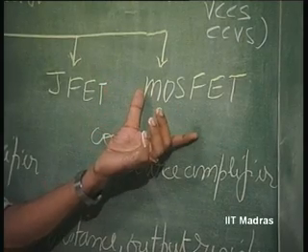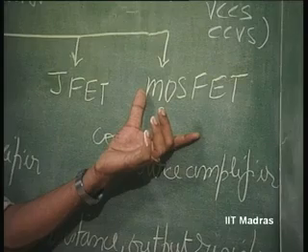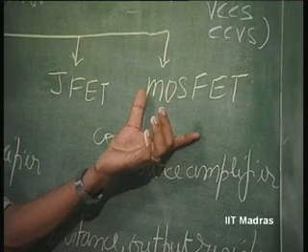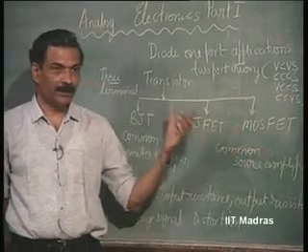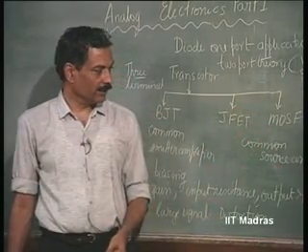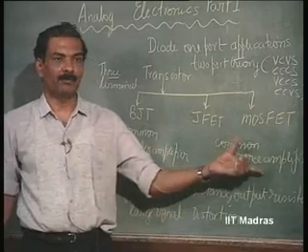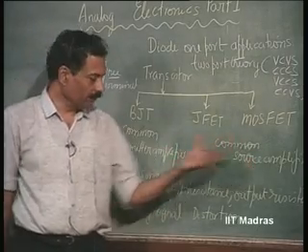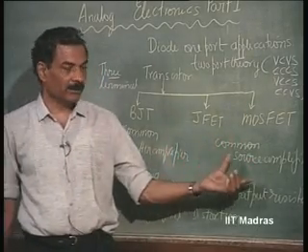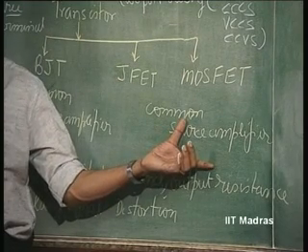The square law of current with respect to input voltage of the MOSFET has been highlighted, and what is the triode region and the current saturation region has been discussed. Then how the common source amplifier, similar to the common emitter amplifier, can be derived, and how using single supply and dual supply you can bias the MOSFETs in an identical fashion.